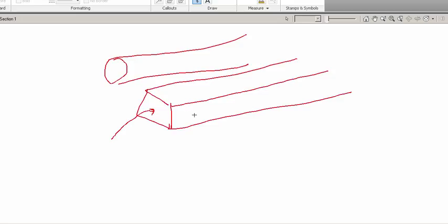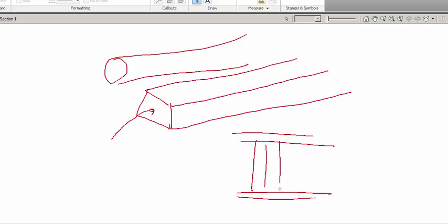Now these don't typically get this big. Your common size you're going to see is like 1/2 inch, 3/4 square, that sort of thing. They're used oftentimes in railing, like in handrails. If you're looking off a balcony and you've got your top rail, you're going to see these little vertical lines a lot of times. And a lot of times if they're steel, they're going to be steel bars that they just weld to the top and bottom rails. This actually keeps a small toddler from being able to stick their head through. There's actually a code on how much space can be between the two.